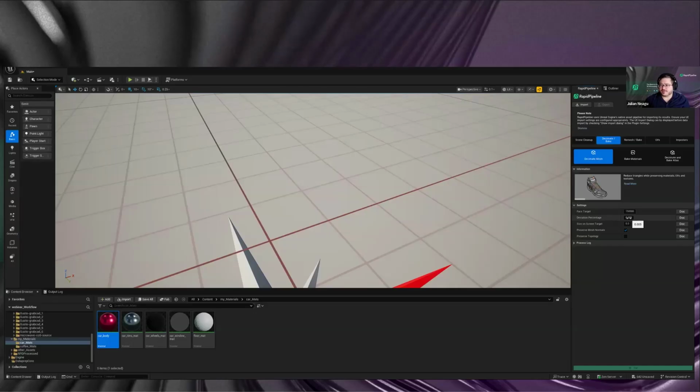And usually this can be paired with the face target as well. So you can say, I want a maximum of 500K faces and a maximum error of, for example, 0.005% of the whole bounding box of the model. And then it gives you a resolution, but it will cut and cap that off at the 500K. A simple pillow would get maybe 30K resolution, while a whole diesel engine or something like that would probably be a calculated version of whatever, 700K, 900K, but would then be cut off at the 500K you set. So that's one of the features we have on top in terms of deviation.